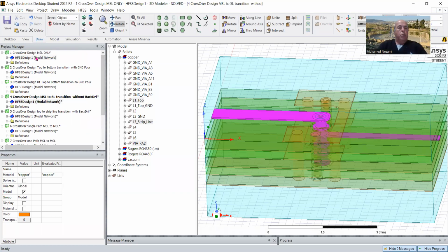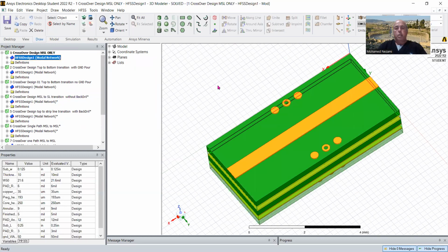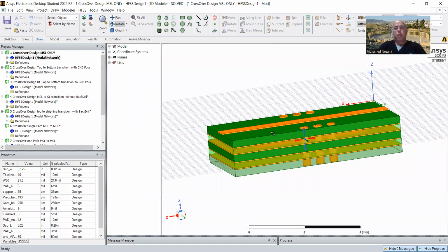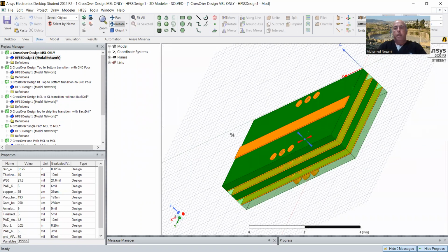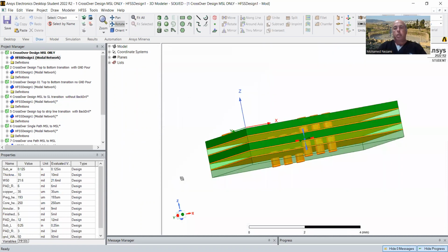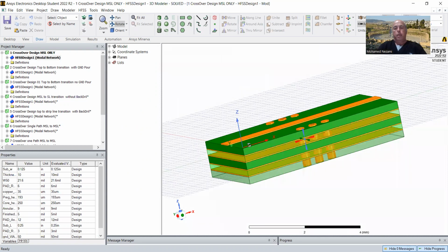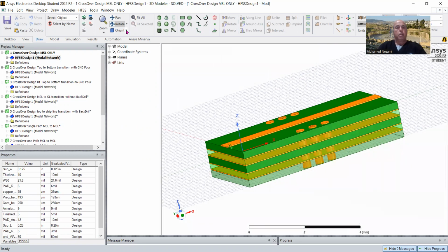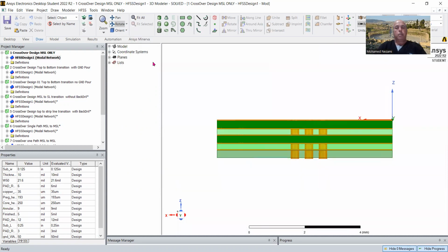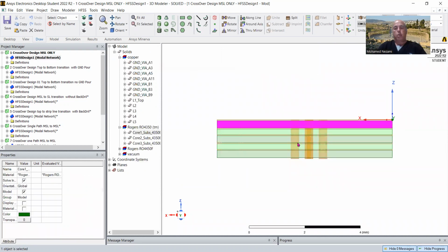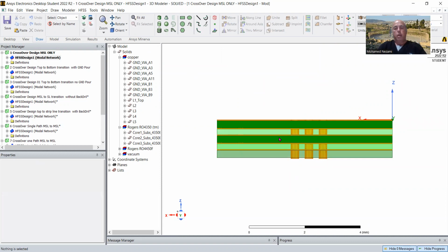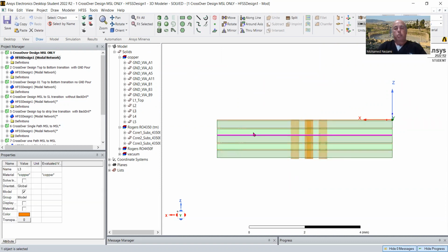It's okay. And just to get back to ANSYS HFSS, the first experiment is this. As you can see, here the substrate is built, the yellowish colors in here. So let's look at it from the side. I have basically this is one core, this is another core, and this is a pre-preg, this one here.